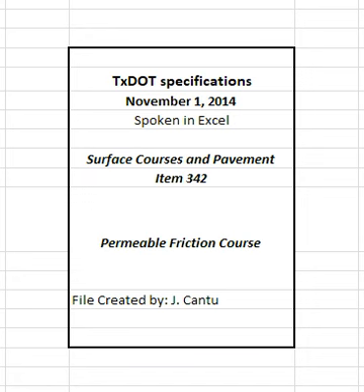4.4.2.2.6 Full approval of JMF1. The engineer will grant full approval of JMF1 and authorize the contractor to proceed with developing JMF2 if the engineer's results for the trial batch meet the requirements in Table 5. The engineer will notify the contractor that an additional trial batch is required if the trial batch does not meet these requirements. 4.4.2.2.7 Approval of JMF2. The engineer will approve JMF2 within 1 working day if the mixture meets the requirements in Table 2 as well as the master grading limits and binder content shown in Table 4.